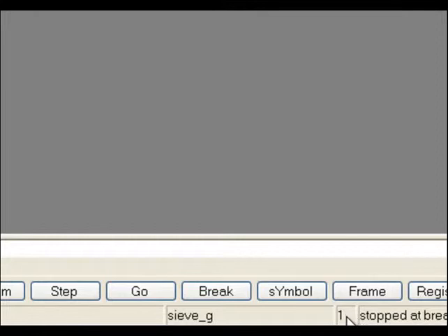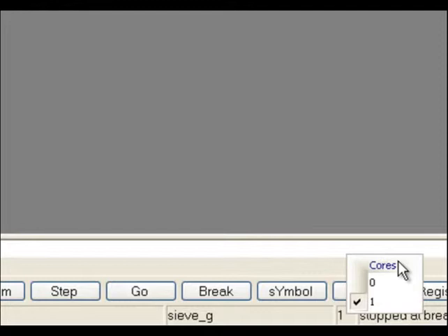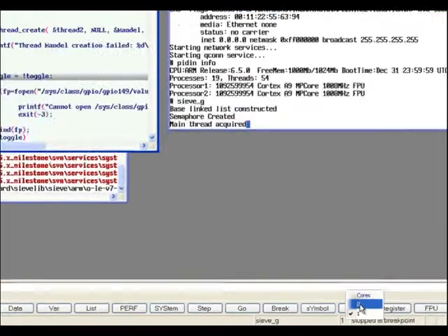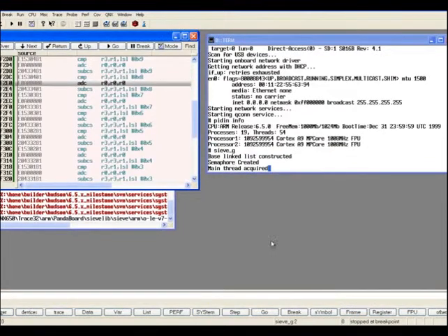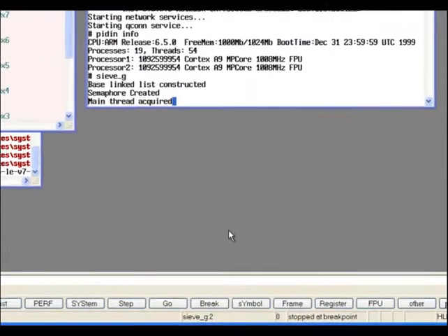Now if we right click onto that field, you can see a small menu with cores, and here you can select the cores that are available in the SMP system. Let's switch to core 0, and you can see that the data list window changed to the place where core 0 is actually running. It is somewhere different, so maybe some other process, maybe the kernel, but of course the CPU 0 does something else. In this case actually core number 0 is also running within our cf_g application, but currently it's running inside a library routine. What's interesting is the display in the status line of TRACE32.